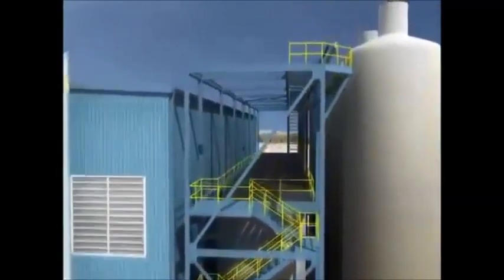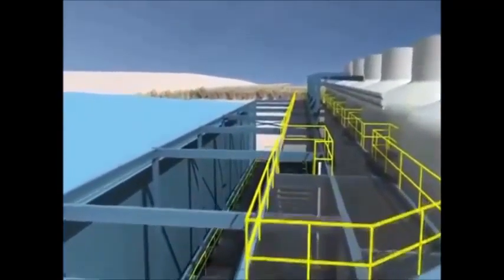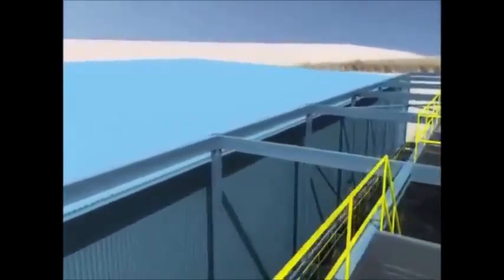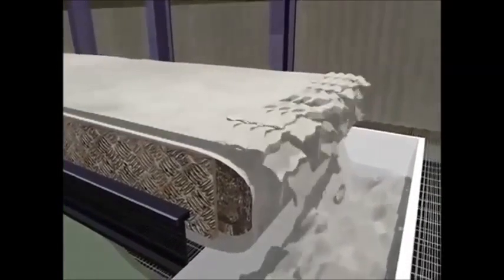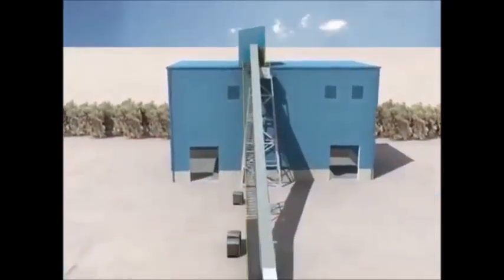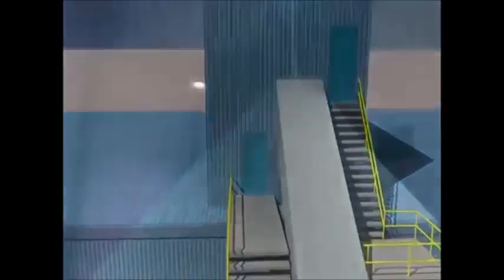The slurry leaving the scrubbers is thickened and pumped through a forced oxidation gypsum, or FOG, system. Oxygen is then added, changing it into gypsum, which is dried, treated, and sent to a gypsum manufacturer to make wallboard. FirstEnergy recycles about 500,000 tons of gypsum each year, enough to manufacture wallboard for 70,000 new homes.